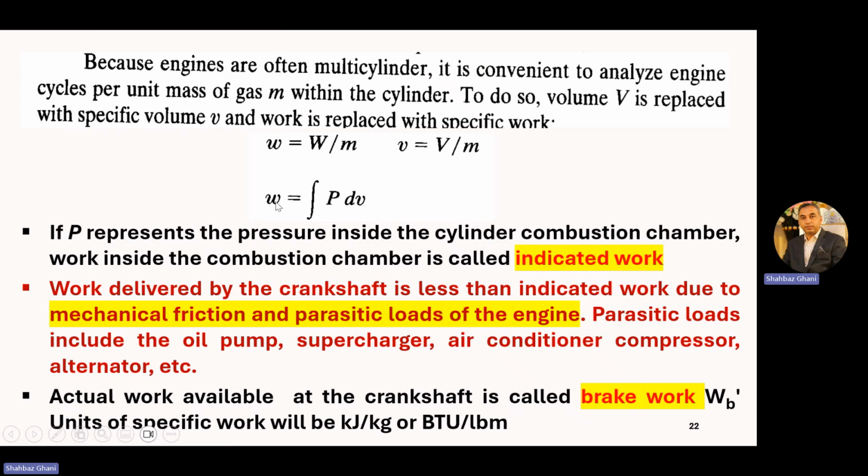So we can write our equation. Specific work is the integral of pressure times the derivative of specific volume. If P represents the pressure inside the cylinder combustion chamber, the work inside the combustion chamber is called indicated work. Remember this terminology, indicated work. The work delivered by the crankshaft is less than the indicated work due to the mechanical friction and parasitic loads